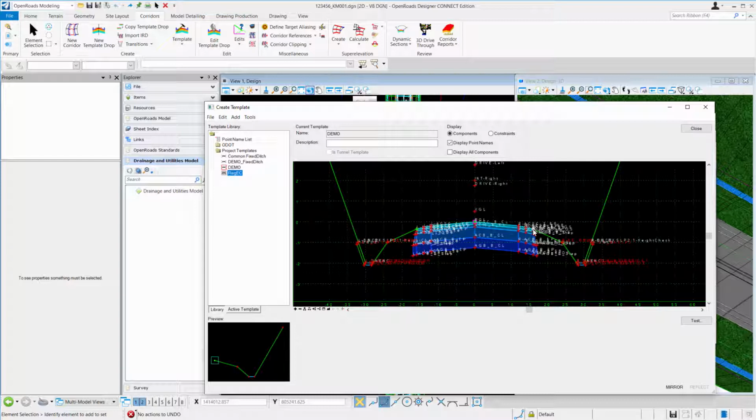Because if they are different, then the profile that you just made for your ditch might not work anymore. It might not solve because it could have pushed your ditch out just a little bit more, which would have maybe made your ditch profile lower. So you do want to make sure they are the same, or you're going to have variables that you didn't account for here. So now that I've quickly double checked they are the same, let me cancel that.